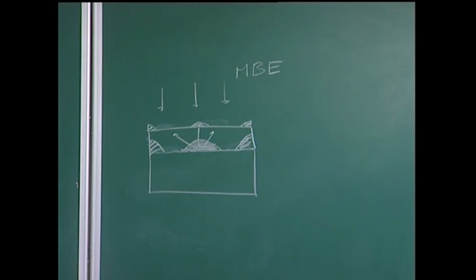Now, let us talk about another important point with respect to residual stresses in a material, and this comes often from the engineering application of materials, that we see that whenever there are residual stresses there is a warping of the component, and often there is a feeling that this implies that residual stresses are harmful for the material. But we also know from a process like shot peening that there can be a beneficial effect of residual stresses. So, we should understand that residual stresses can be beneficial or detrimental depending on the situation. So, we will take an example of both.